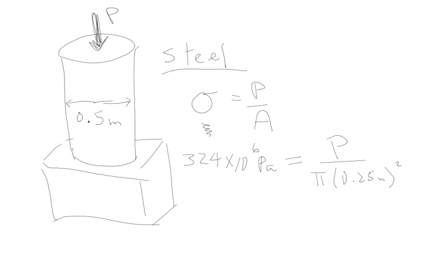That means if you apply a force equal to whatever this value of P is, then you go right up to the breaking point. And once you know that, then this is what you tell your customer: do not apply any more than this value P. If you exceed this value P, then you're exceeding the strength of the material and the material will break. If you apply less, then of course it's going to be fine. So that is pretty much the last variation of the design problem.